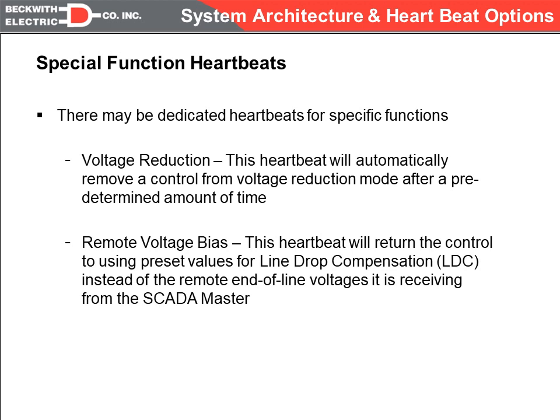Now, there are a couple other heartbeats besides the normal one for IVVC, and that is because we have dedicated applications that need separate heartbeats. The first of which is voltage reduction. So if you do remote voltage reduction to your regulator and LTC controls, and you place them into a reduction mode and then they lose communications, you don't want them to permanently stay in that reduction mode.